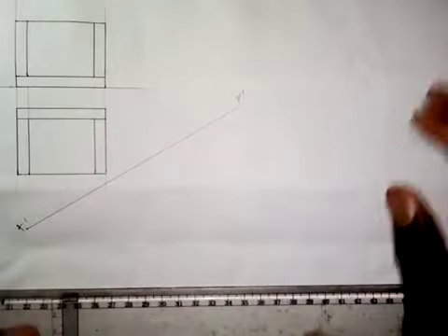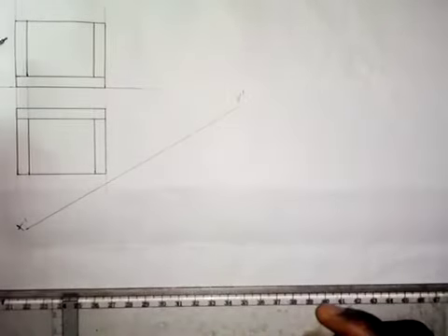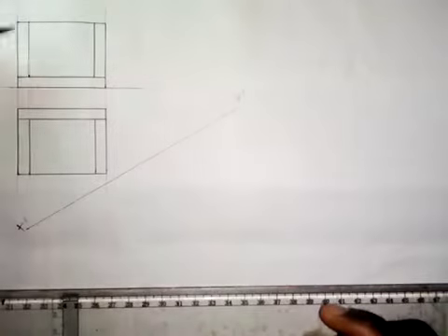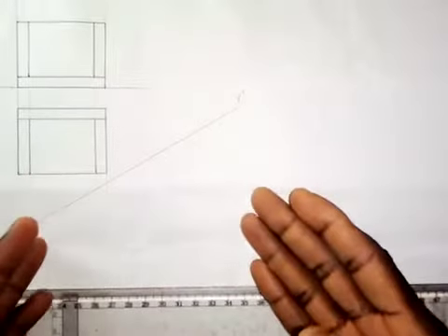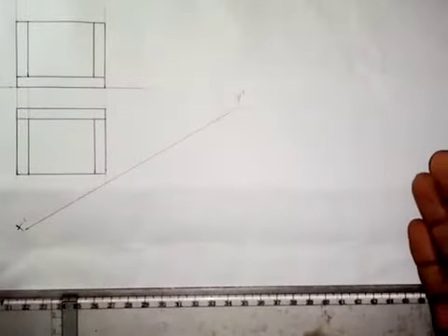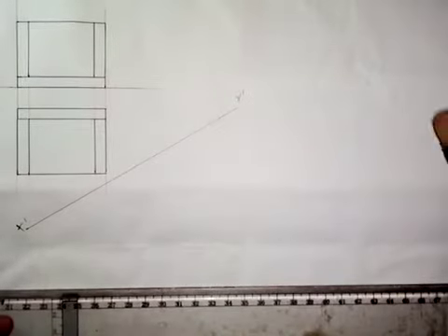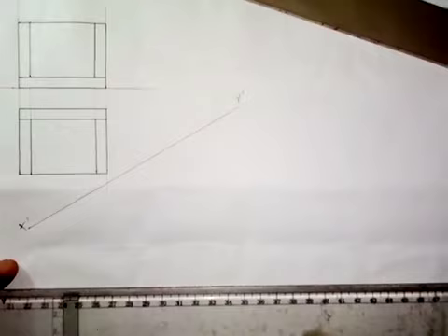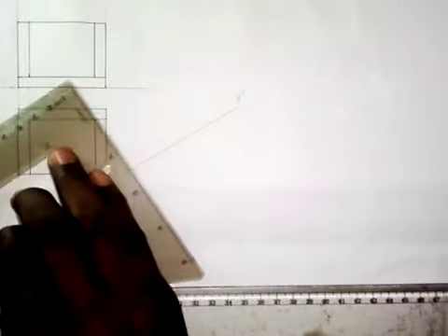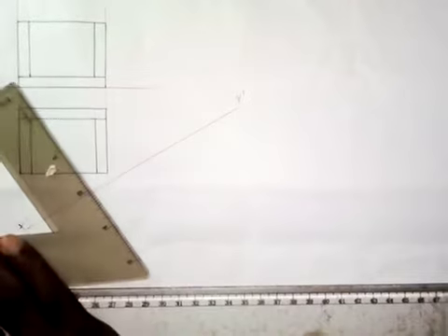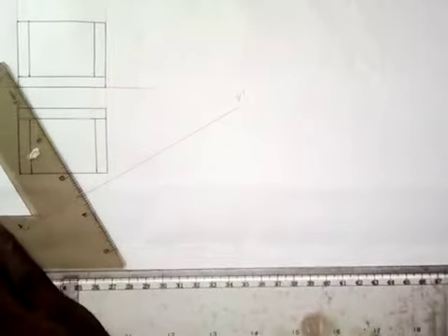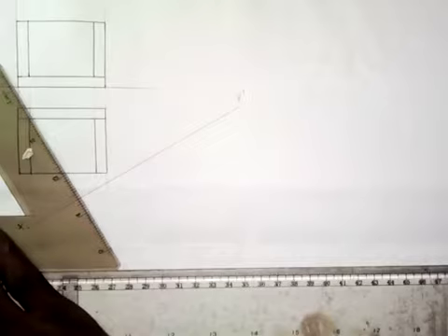The next thing that you need to do now is to project lines from the front elevation to draw the auxiliary plan. You have to project lines from each point on the given elevation onto this plane, and those lines will be at right angle to the given plane, that means perpendicular to it. As we have drawn this line with the 30 degree set square, for us to draw the lines at right angle to this plane, we have to make use of the 60 degree side of our set square. So I'm going to pause the video while I project the lines.